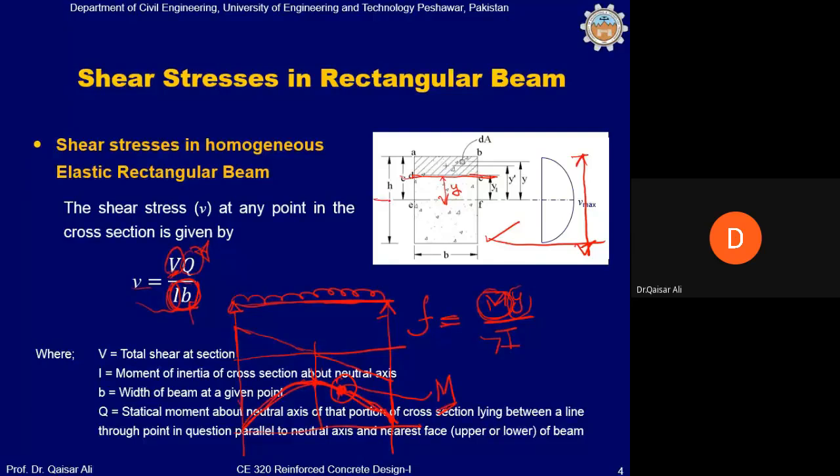This is the neutral axis. And you know that the stress diagram varies like this through the depth of the beam, in the linear elastic range. So we have zero stress when Y is zero. Flexure stress will be zero even if M is maximum. But if M is maximum and Y is also maximum, this can happen at the center of the beam in this particular case, in the extreme fibers, when Y is h/2, either in the compression or in the tension zone. Because I is constant, so I will be constant if the width and depth of the beam do not change along the length of the beam.